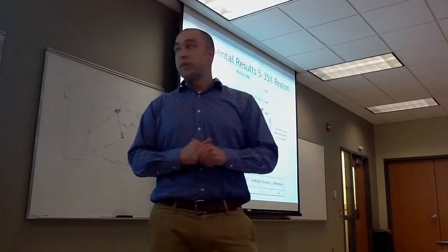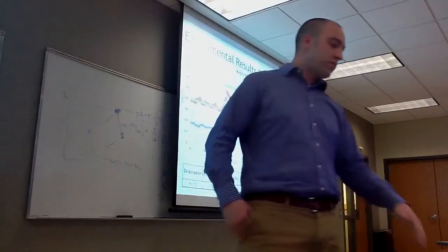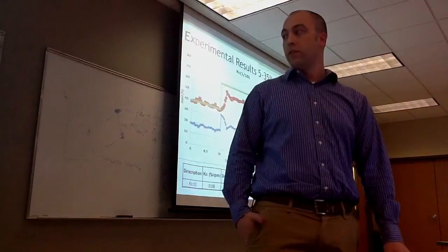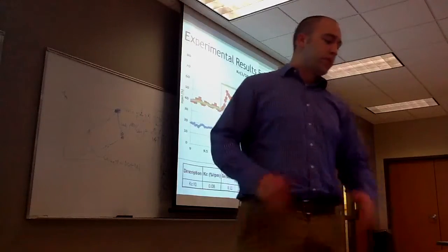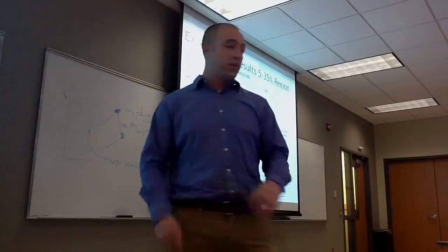This is the 1/10th decay gain. Found that to be 0.08 with a decay ratio of almost a tenth. It's oscillatory with settling time of 0.5 seconds. It has an offset of 83 RPMs.